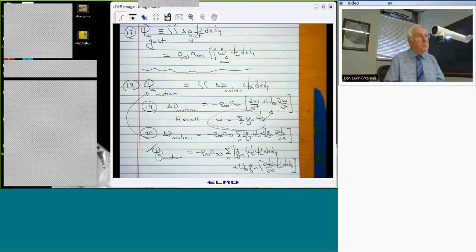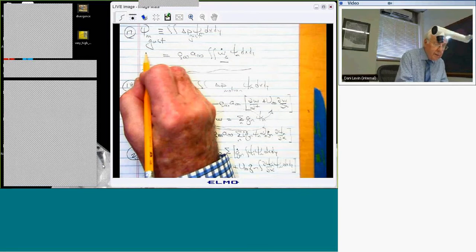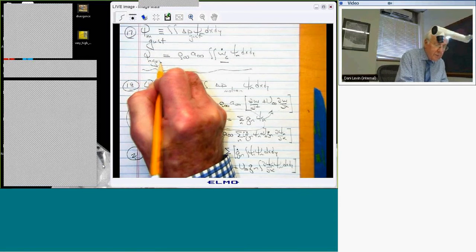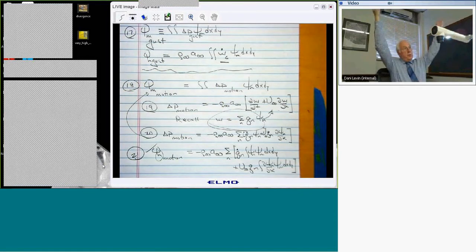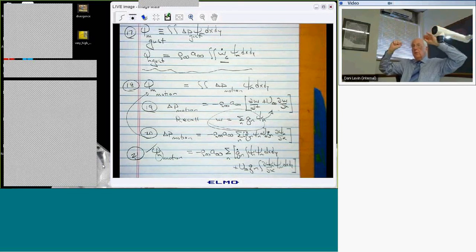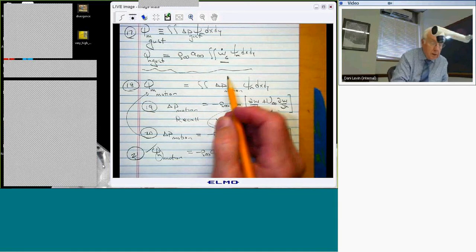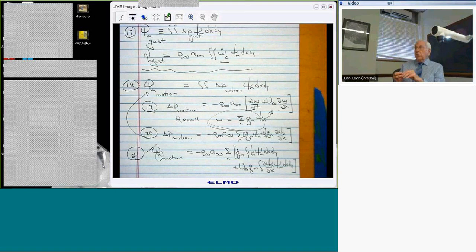So now we can actually solve a problem. If we take these results, I'll call this 21, and take 21 and 17 and put them into equation 1, which was the equation of motion for the structural modes, I have equations which in principle I can solve for these coefficients, the small q. And I can solve for gust response, and I can solve for the flutter condition. We've got time to do at least some of that today.